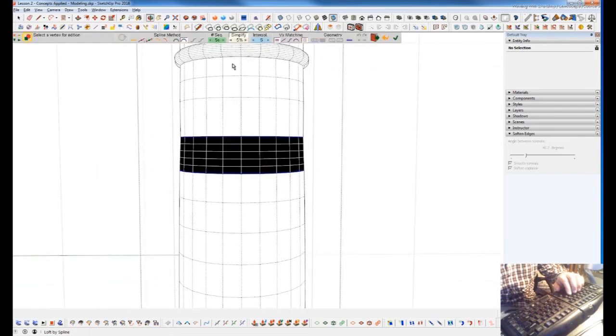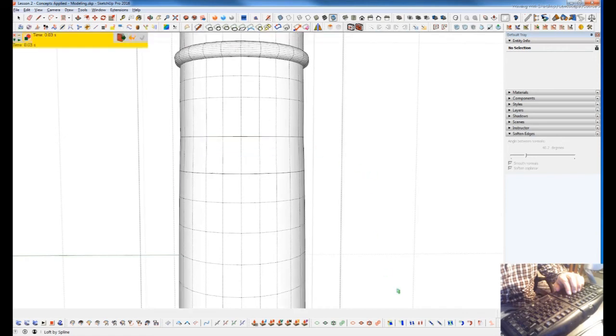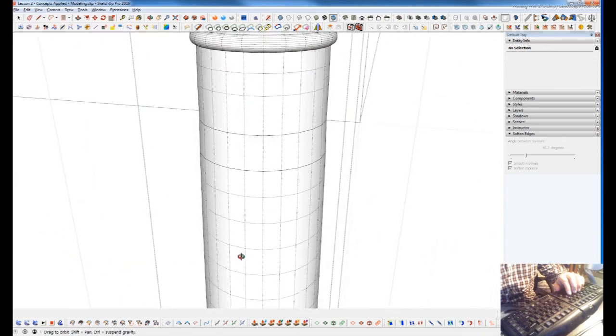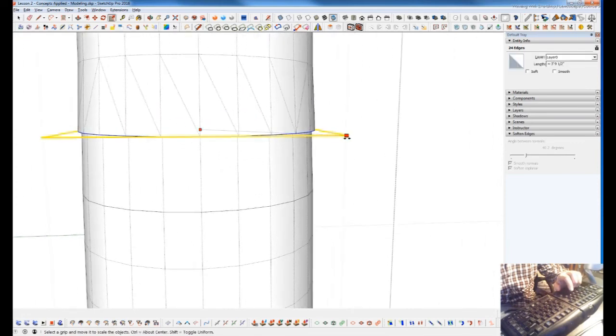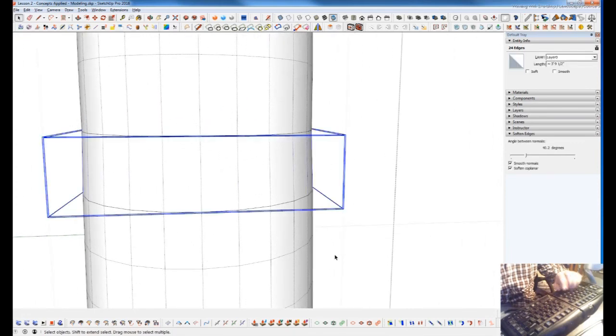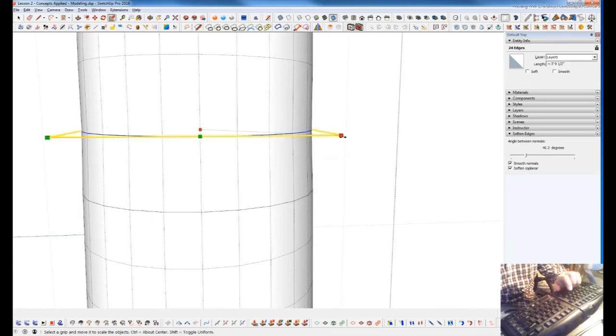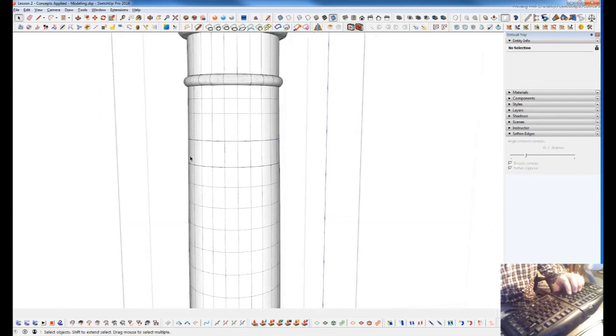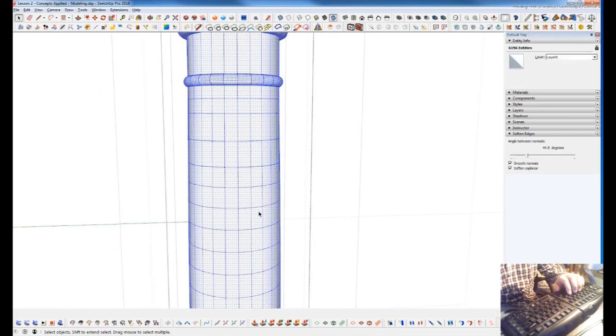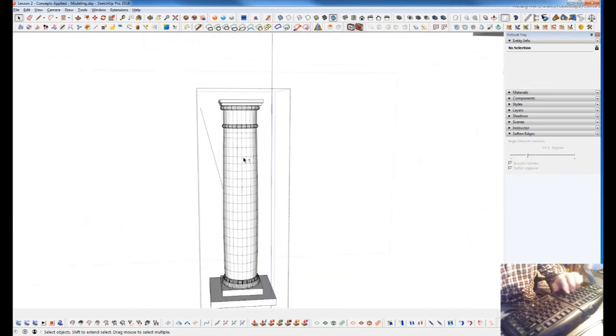Just select both, and I'm going to run Curvy Loft. It's just going to make the junction there, and I'm going to take this down to 1. And this looks a little weird. I'm just going to grab this and scale this just a little bit. Curvy Loft is in a group, so I'm going to explode that first, and I can scale this out just a hair. Not too much. Scale that in. That's how it looks right visually, and try smoothing one more time.